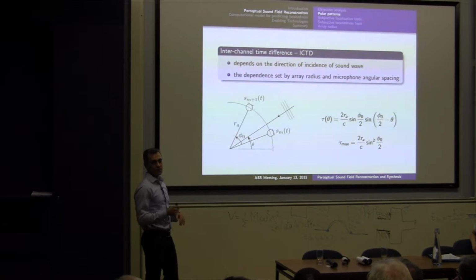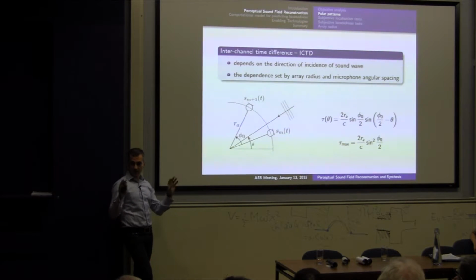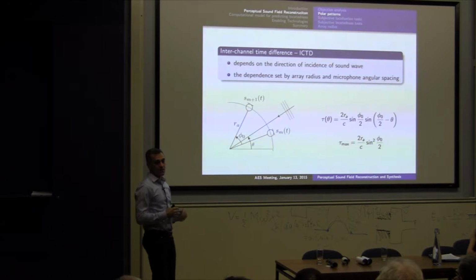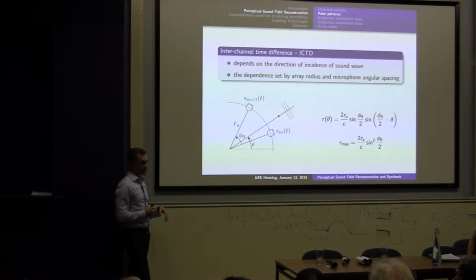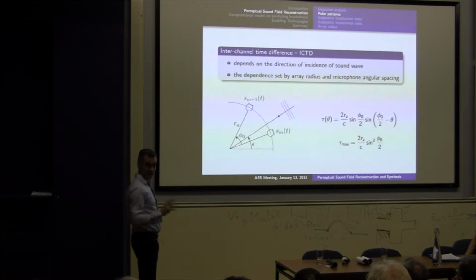And now what we want to see is how to design those polar patterns so that the time and level differences captured by those microphones are such that when we play them back using loudspeakers, we have the impression of the sound wave propagating in the correct direction. So we need to provide time and level differences properly.